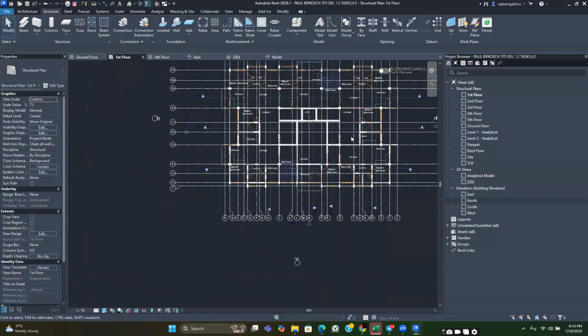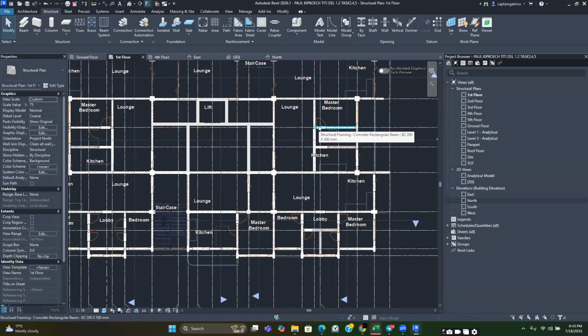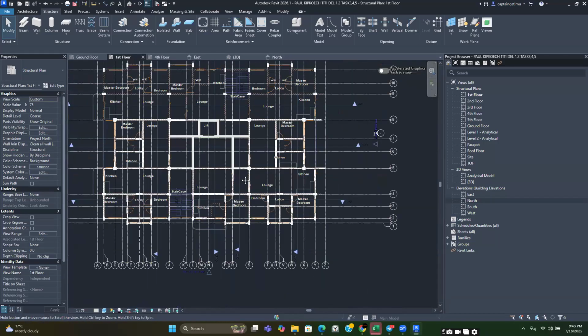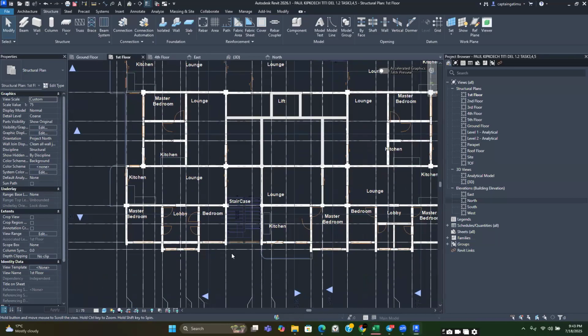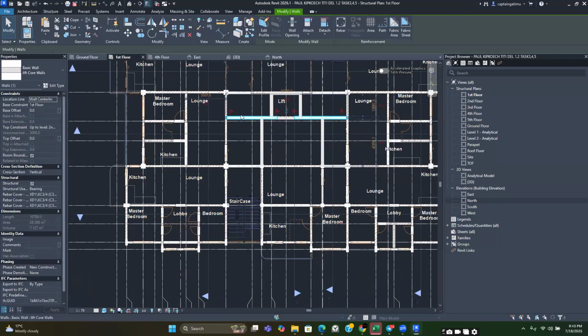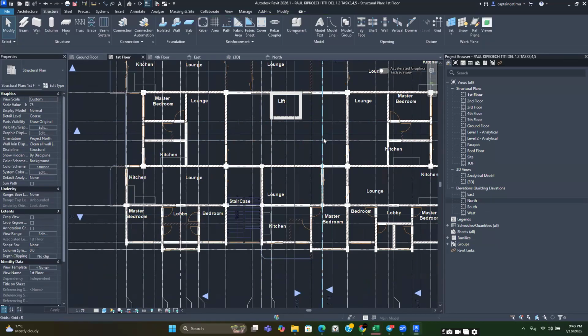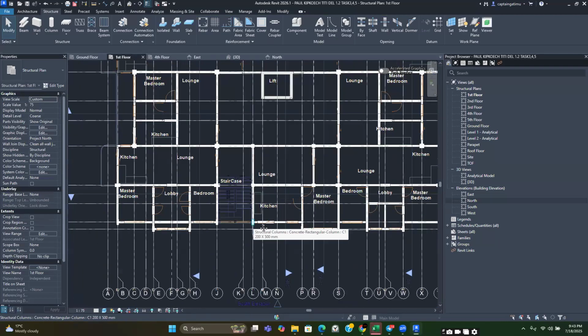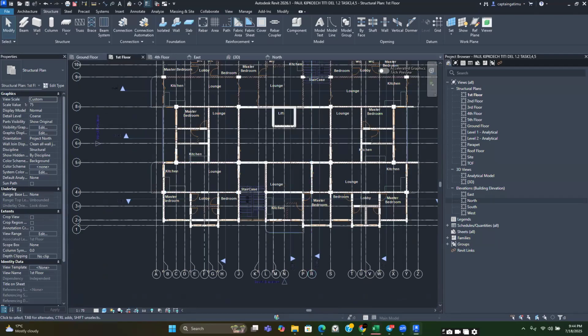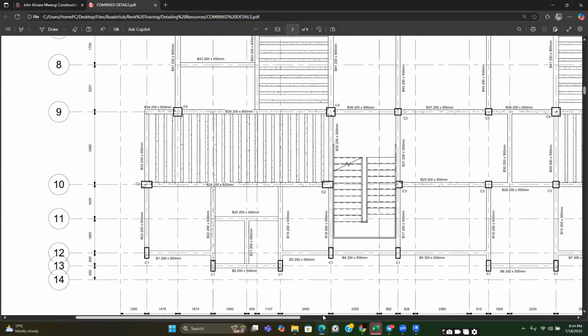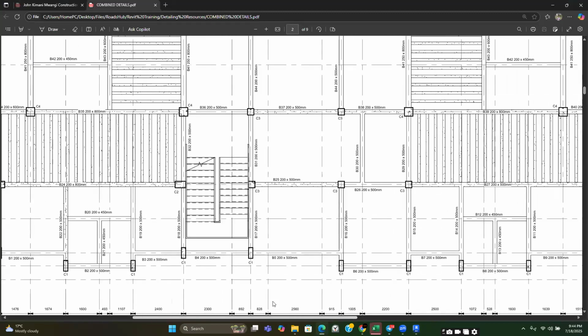And you're good to go. So you can see how modeling the beams in one cross section is faster than using different cross sections. But you cannot stop here, since after you design your structure, you are going to notice that you need different sections. So what you can do at this point, after you have modeled all your beams in the same section, is go to the PDF and identify the areas where you need a different section.